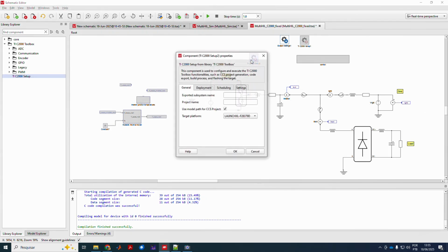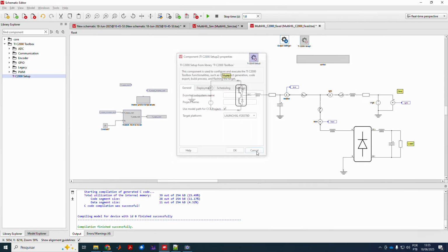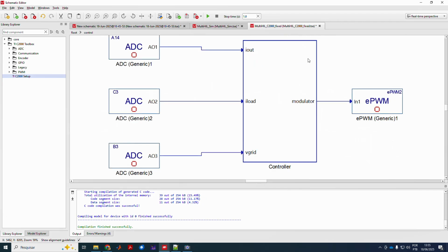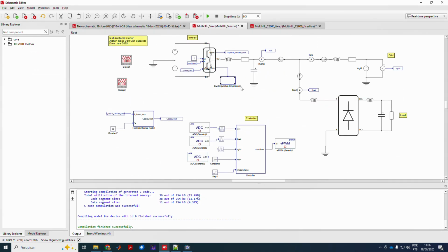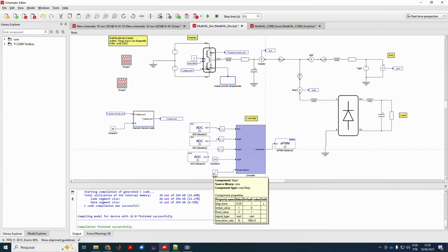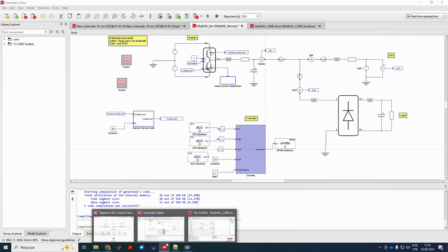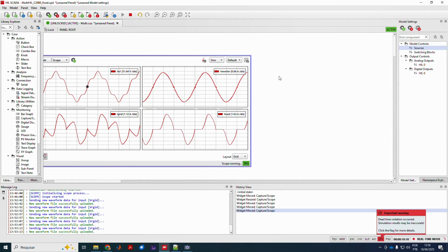And if you take a look very fast here, you can change microcontrollers. You can use this classical one, the 335, but I think it's really interesting to convert all my blocks into code without opening Code Composer, because I can test everything here: power losses, digital control, the full system. I can switch here from one mode to another. I can use SCADA later to create a lot of widgets here to change amplitude, change the mode of operation, modify frequency.